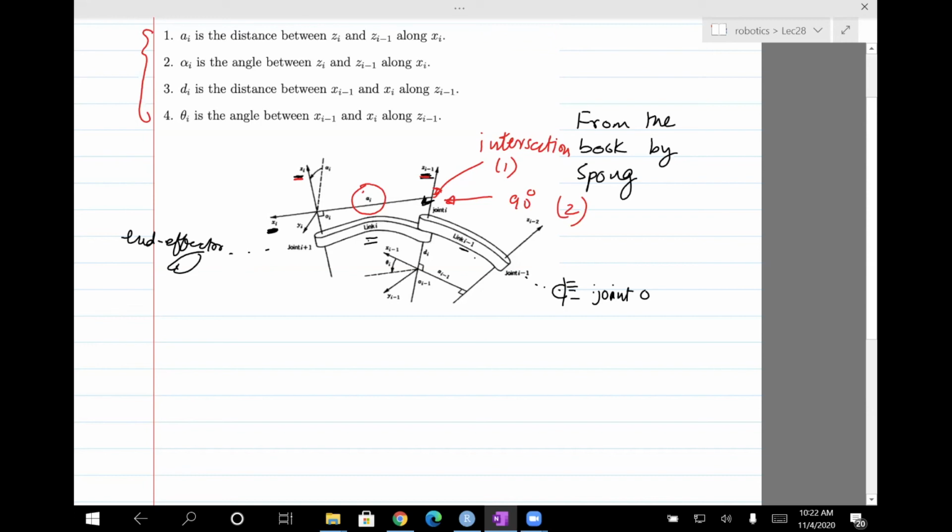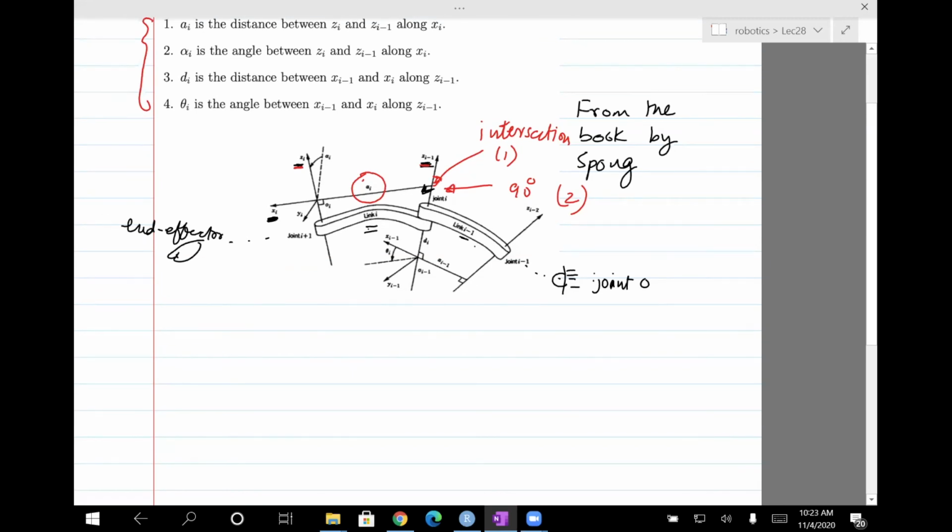The third step is very trivial. It's just taking that H matrix, which I wrote down, which has those four multiplications, and then getting the transformation for a particular link, and then just putting these H's for each link to build the kinematic chain for the whole manipulator. So there are three steps. Step one is the hardest, probably, because it's about defining the axis. Step two is also similarly hard, but then step three and everything else is very simple. So once you have those two steps, everything becomes easy.